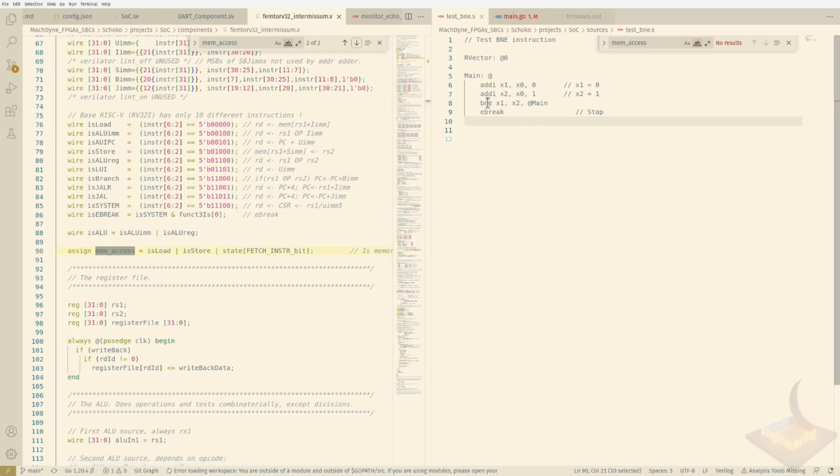What was happening, if we look at this little example here for this assembly program, is that when we had a branch backwards in the instruction, the address register actually contained the instruction itself, and it was causing my SoC to inadvertently activate I/O, which wasn't good.